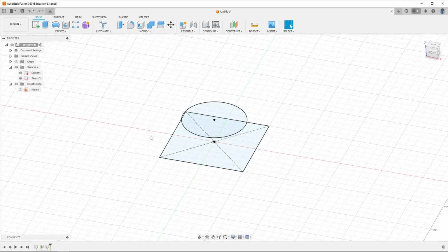And now what I will say is that you have to be careful sometimes, because we're going from a shape that has sharp four corners and four edges to a round shape, and it's going to do its best to make this happen. But if you kind of overdo it sometimes, depending on how exotic your shapes are, it can cause kind of weird warpage in your objects. And in the worst case scenario, it might not actually be able to generate the shape, but in this one it will be able to do that successfully.